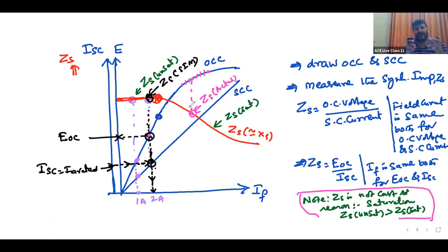In actual working conditions, the field poles are a little saturated, but we are taking the unsaturated portion. So ZS is more, and when ZS is more, regulation is more. So the conclusion is like this. Listen. The reason is, in this method ZS is measured for the field current corresponding to rated short circuit current, which belongs to the unsaturated portion, and this ZS is more than the actual ZS. That's the reason regulation is more, because regulation is proportional to ZS.